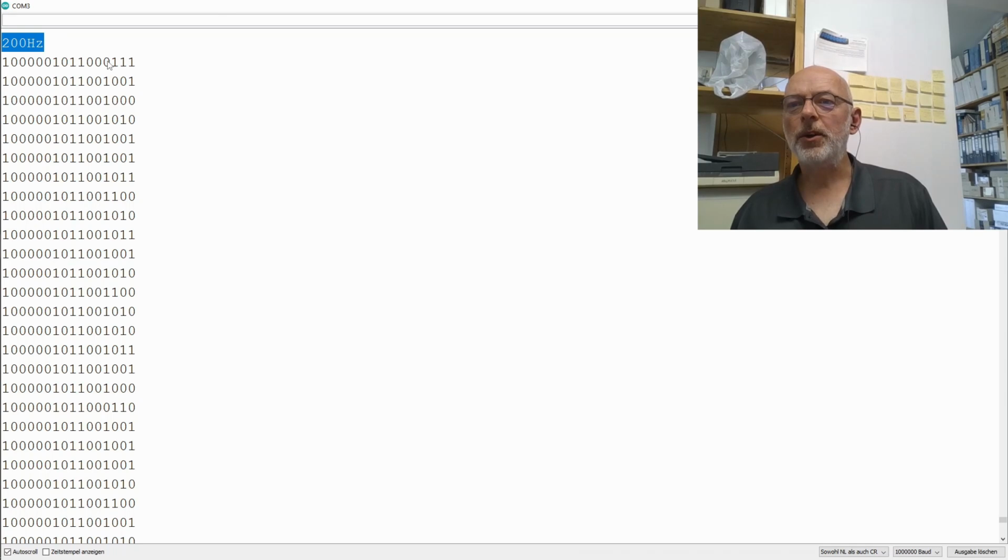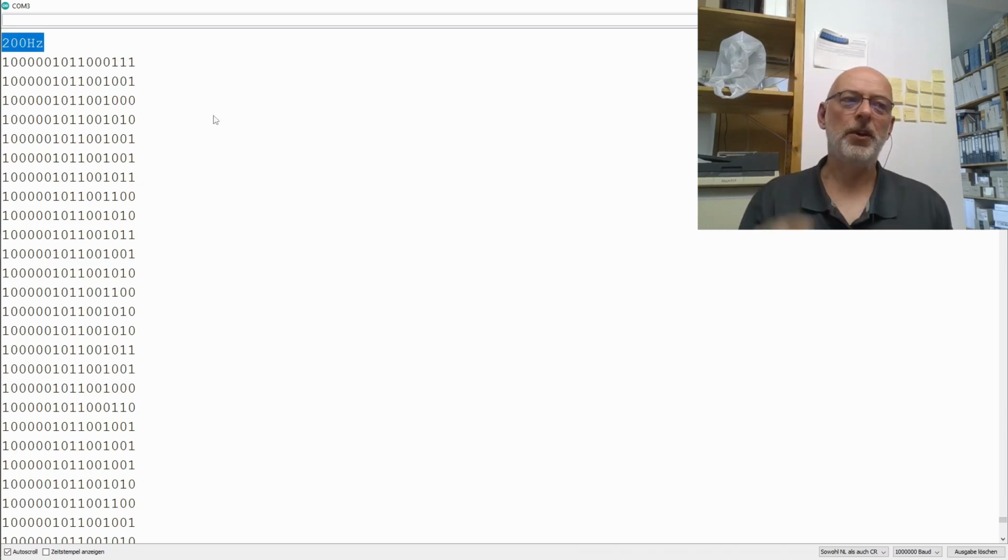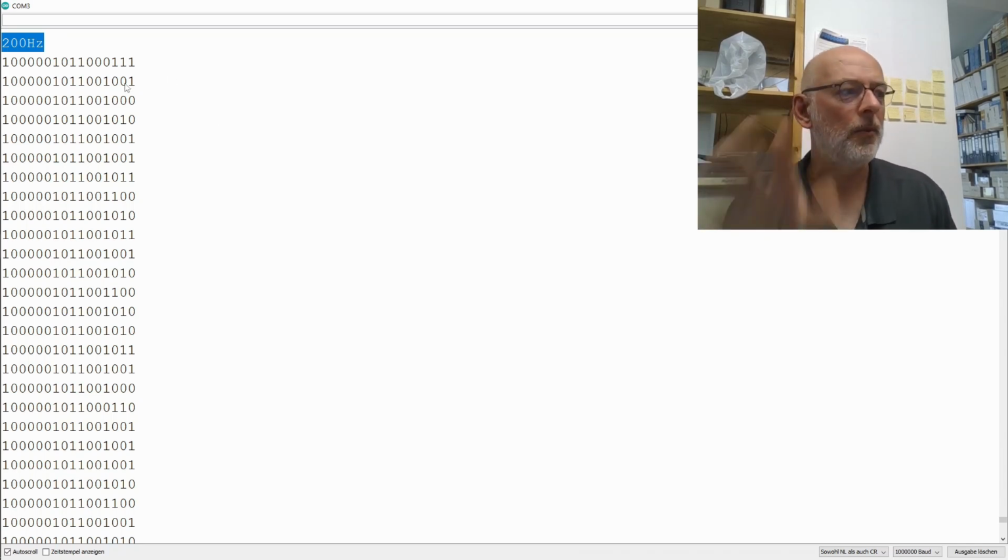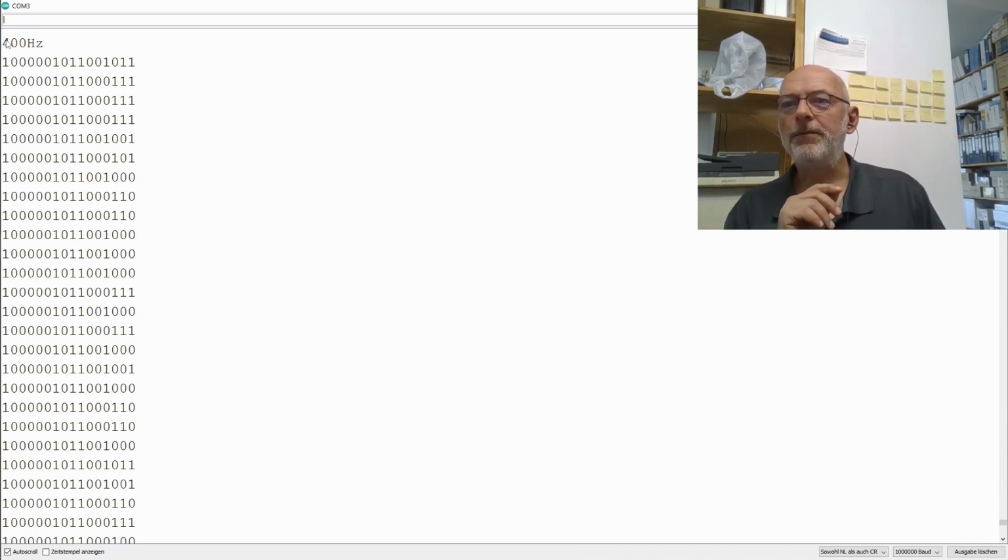At 200 Hertz, the 4th bit starts to flip now and then. We can go a little bit, but yeah, it's almost stable. Okay, there was one flip up here. So let's call 100 Hertz 2.5 bits and that 3 bits. At 400 Hertz, clearly our 4th bit is now flipping around in the breeze, so 4 bits of noise.